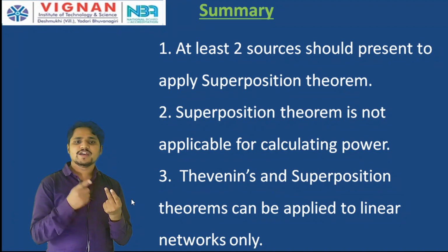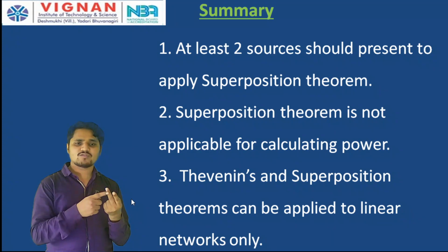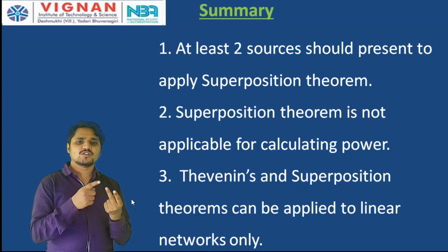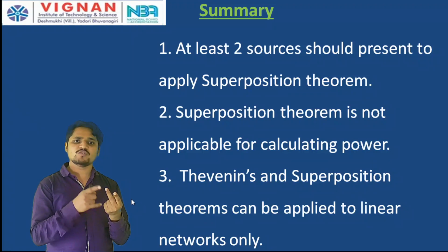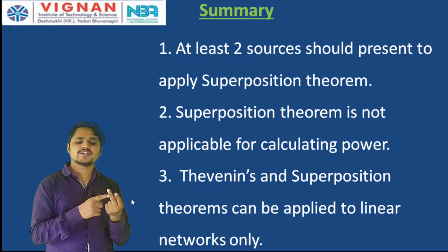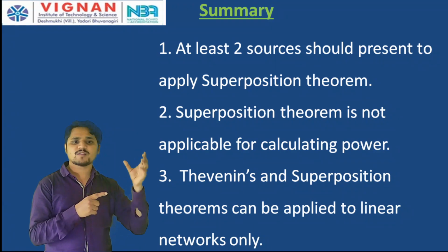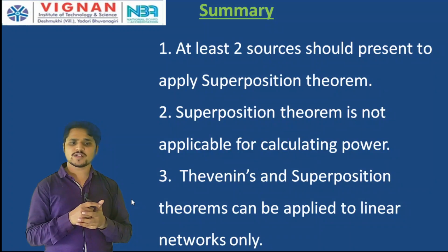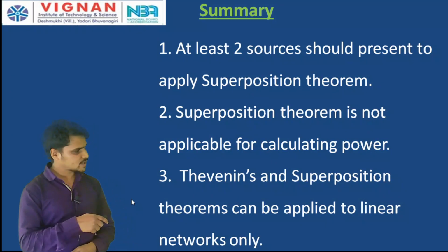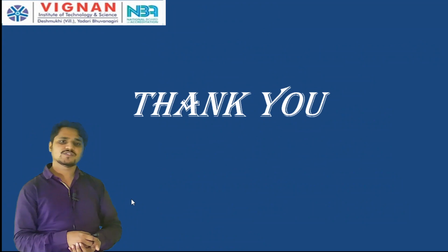Thevenin's theorem says any linear network with open output terminals can be converted into an equivalent circuit consisting of only one voltage source, V Thevenin, the open circuit voltage, in series with a resistance or impedance, R Thevenin or Z Thevenin, the equivalent resistance or impedance seen from the same open circuit terminals. So this is today's lecture on the superposition theorem and Thevenin's theorem.